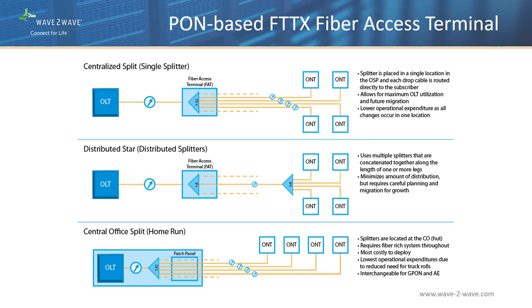As the amount of fiber dramatically increases, the importance of properly managing fiber cables becomes a more crucial issue. Telcos use various approaches, including single splits, distributed splits, and centralized splits within the CO. The manner in which fiber cables are connected, terminated, routed, spliced, stored, and handled will directly and substantially impact the FTTX network's performance, stability, and more importantly, its profitability.